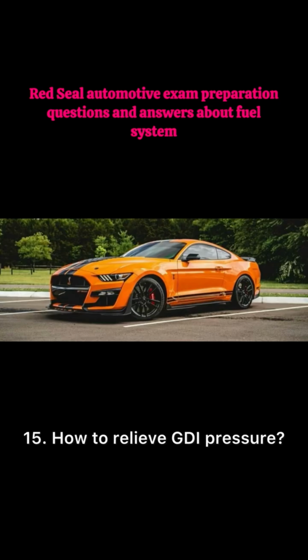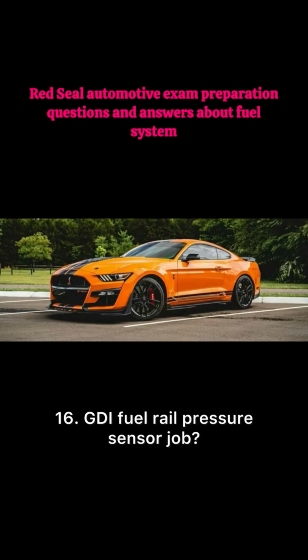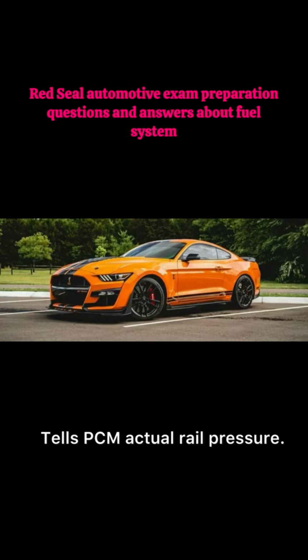15. How to relieve GDI pressure. Scan tool disable pump plus run engine, or wait. 16. GDI fuel rail pressure sensor job. Tells PCM actual rail pressure. 17. P0191 code. Fuel rail pressure sensor issue.